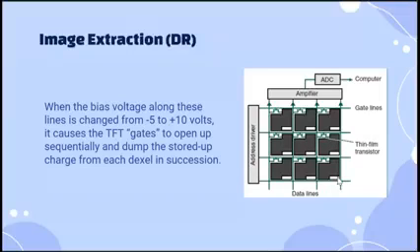So once the voltage increases to +10 volts, in order for the voltage to be carried from this area towards the thin film transistor, the change in voltage in the semiconductor material here causes a channel of conductivity. So that means it will now conduct electricity or voltage. Okay, so since it now conducts voltage because of the +10 volts in the storage capacitor, the voltage here will travel from this area through the semiconductor towards the thin film transistor and towards the data lines towards the amplifier.